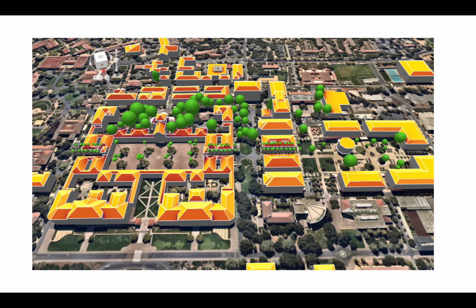So to sum things up, today we provided an in-depth look at irradiance and several related concepts. First, we defined the key terms related to communicating available solar energy at a particular location, such as irradiance, insolation or radiation, solar access, tilt orientation factor, and total solar resource fraction. We then explored the three components that make up irradiance, which must be calculated to get the most accurate irradiance measurements: direct beam, sky diffuse, and ground diffuse.